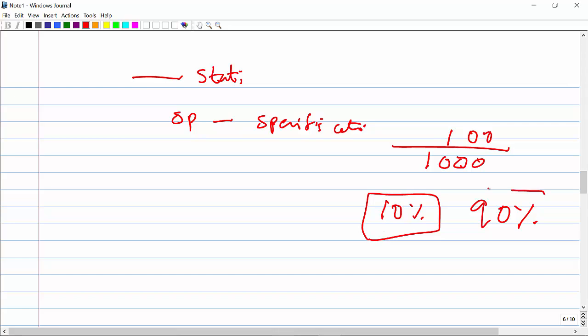So the Monte Carlo simulation gives you an estimation of the yield of your design, and I repeat, it is a statistical analysis that randomly picks the mismatch and the process, and it gives you a lot of information that we will cover during the simulation in Cadence. So let us go to Cadence and do the simulation of the Monte Carlo analysis.